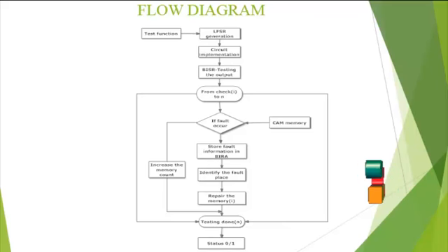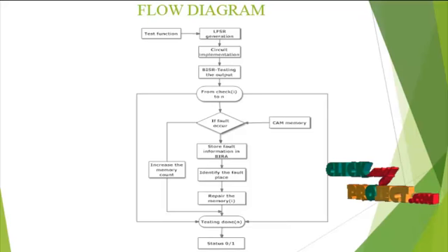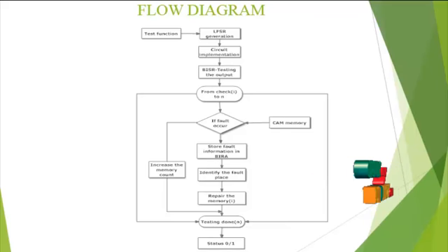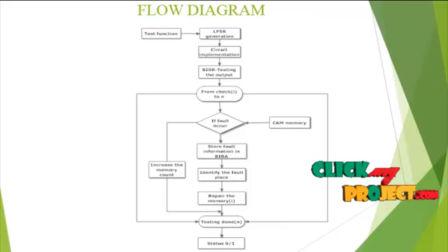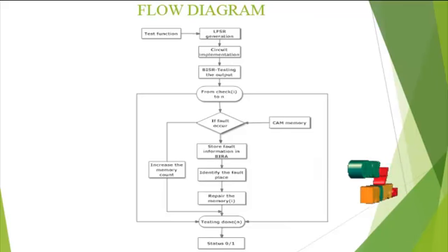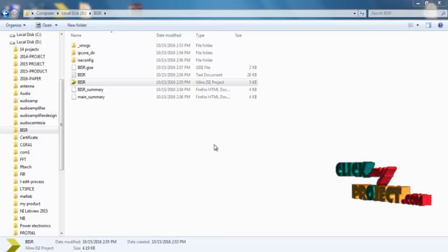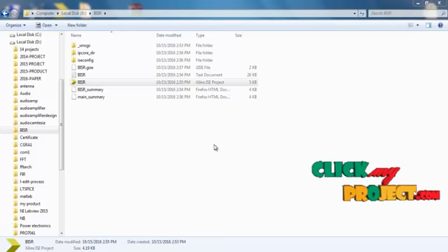If a fault is detected on the largest memory, the fault information is sent to BIST through the port fault_info. Because memory can be repaired by BARA sequentially, if the largest memory is faulty, the faulty information is sent to BARA during the parallel test. The BARA searches for the redundancy cells and repairs the faulty cells. Finally, we are going to see the output for our product.